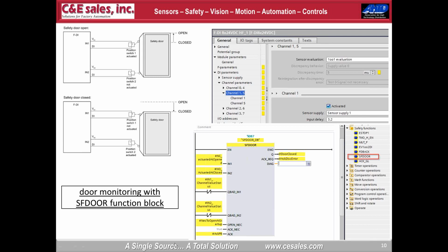So you see, this is the first instance where the function block has Q bad inputs, where in a 1200 or 1500, we're actually going to supply it the negated state of the value status of those two input devices. What it's doing here in the function block is, should the module that's connected to the inputs fault, you don't have to reset this particular function block.